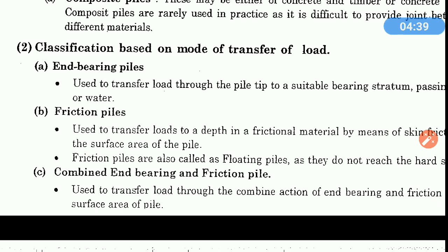Then classification based on the mode of transfer of load. Mainly a pile can transfer load in two ways. One is by skin friction. When we bore or cast a pile in sand, it will exert some force on the adjoining soil, and through Newton's third law, the adjoining soil also puts some force on the pile from the surrounding area.